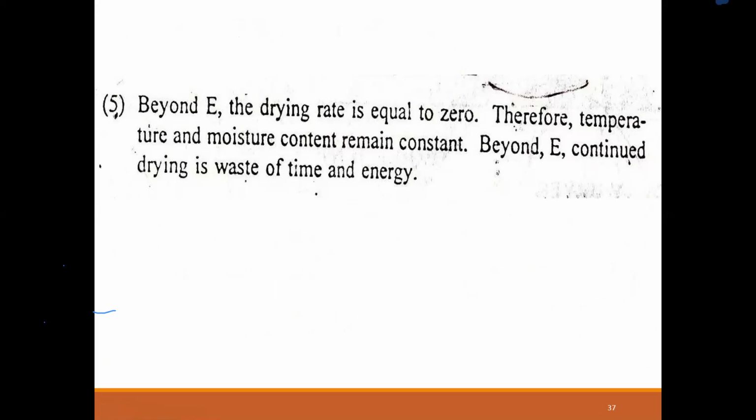After that, the temperature and the moisture content remain constant, right? So if you continue drying when no drying is possible, it is a total waste of time and a total waste of energy. You understand this curve? It is very important from the examination point of view. Hello? Can you hear? Yes, sir.